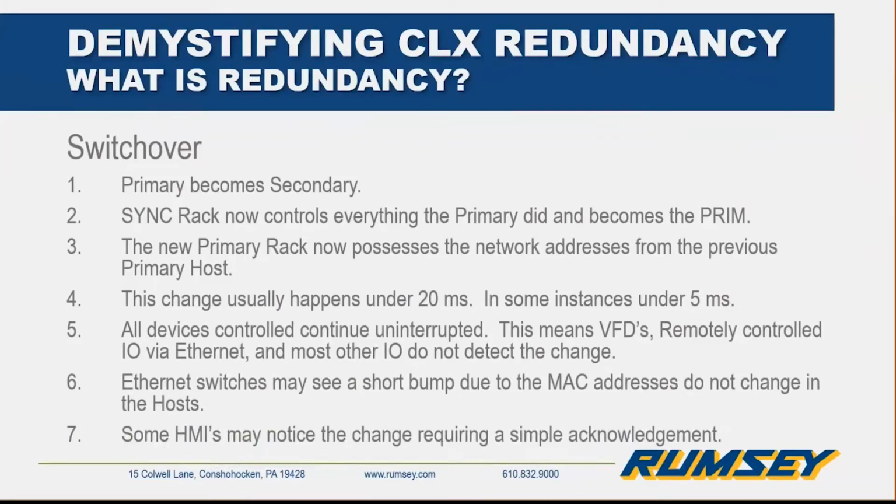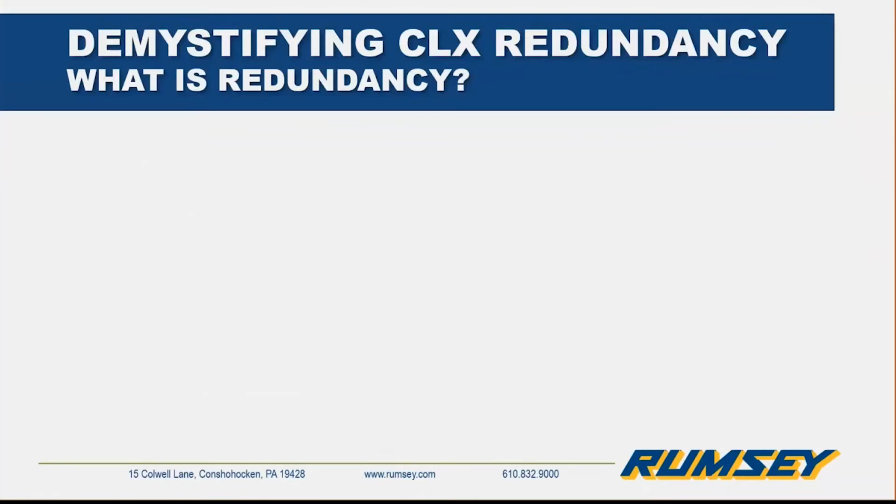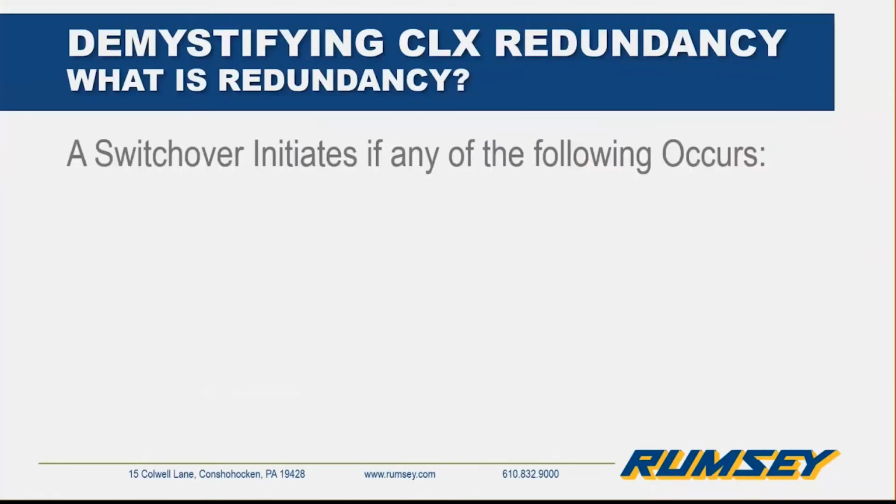Now, some HMIs, and it's not uncommon to have a PanelView Plus, for instance, connected to the redundancy system, and you'll just briefly notice where that little information screen comes up. As soon as you're able to hit close, you'll notice that it's already reconnected. It's very, very fast, but because it is a class 3 device, for the most part, that's why it occurs.